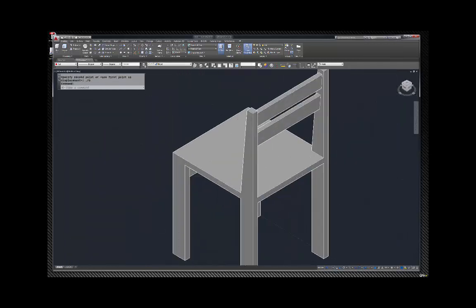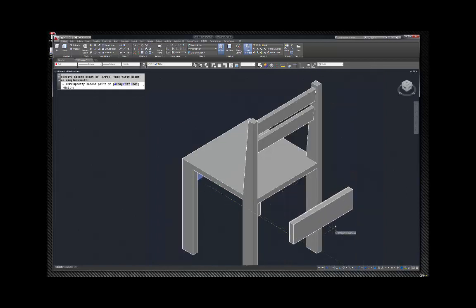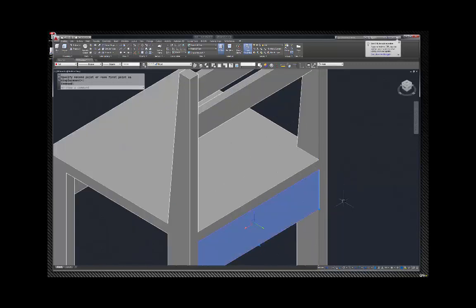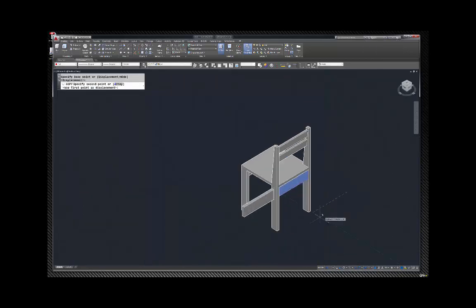I know for a fact there's got to be one back here too, so I'm going to copy this. Just bring it back, okay. I'm going to move it, put it on the geometry, use my geometry to move it, and move it in 0.25. Okay, take that, I'm going to copy this, bring it out here, rotate this using my 3D rotate, pick a corner, pick the blue, swing it around. There it is. Move it in. Okay.